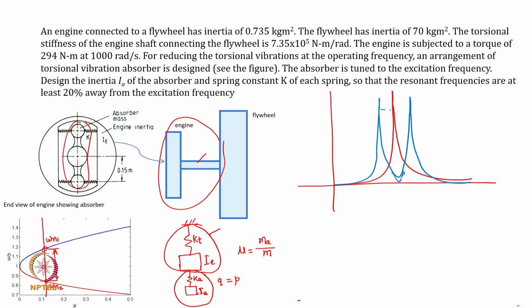But it would be important to look at this frequency range. If it is too short, which is typically the case, and your operating speed fluctuates, then what happens is that although you have designed it for this speed, because of the normal speed fluctuations that can happen in practice, you can actually get into large amplitudes because of the closeness to the two new resonances. So, this becomes a challenging part in this case, and to get around it,